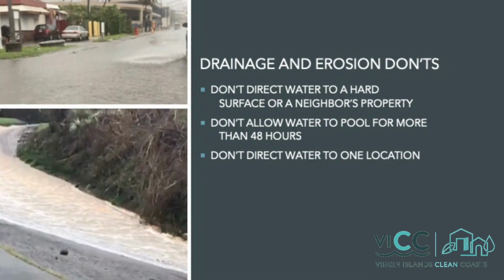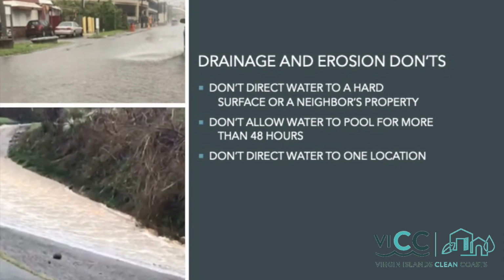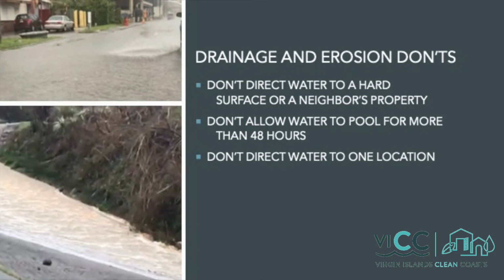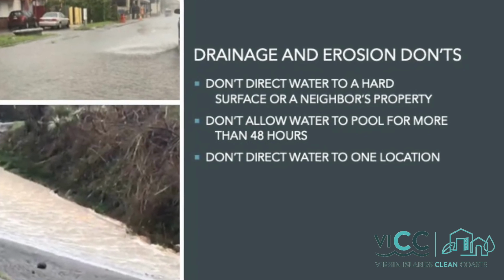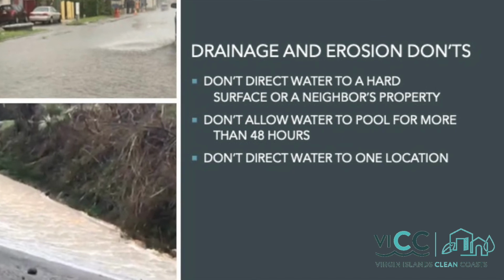Drainage and erosion don'ts. Don't direct water to a hard surface or neighbor's property. Don't allow water to pool for more than 48 hours. Mosquitoes complete their life cycle in 72 hours. Don't direct water to one location.